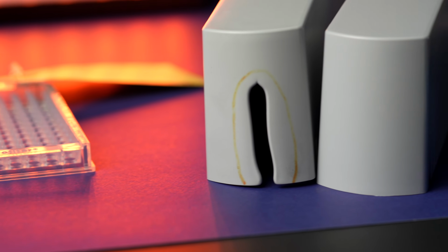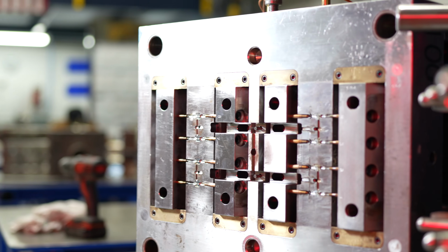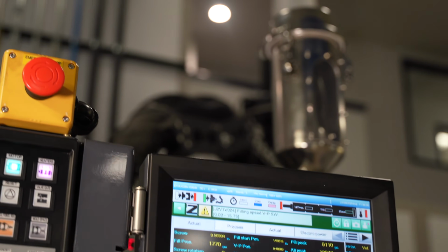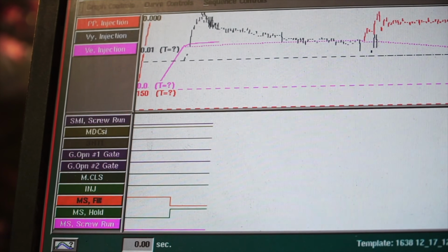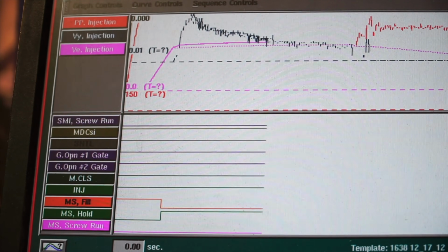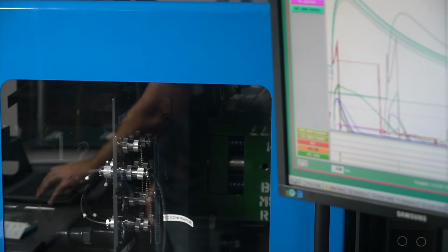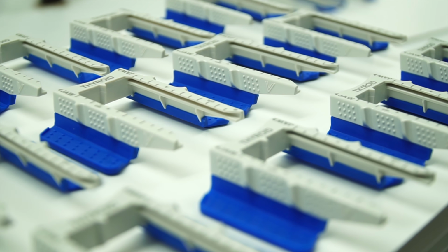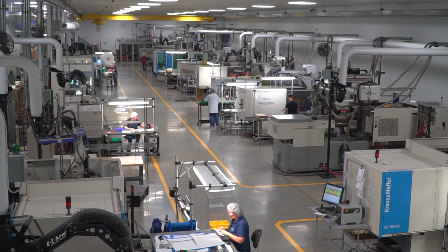Short shots may also be caused by inadequate venting in the mold, which can trap air pockets, a frozen flow channel that may need to be cleaned, or simply not packing enough resin into the mold cavity during the injection process. As you can tell, much of this has to do with the injection molding process, which involves many complex variables. So here at Crescent, we utilize a proven process called decoupled molding, and we have a number of certified master molders who are able to optimize the process not just to produce a good part, but to do it as efficiently as possible over long production runs.